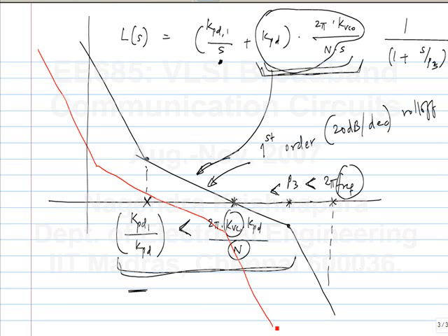Settling time will increase. Actually, that's a very good point, that the closed loop bandwidth of the red system is much less than the closed loop bandwidth of the black one. So that is an argument for pushing it to the right. Now, if you push it too far to the right, you will have problems with reference feed-through, okay?